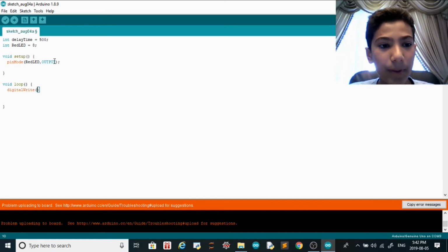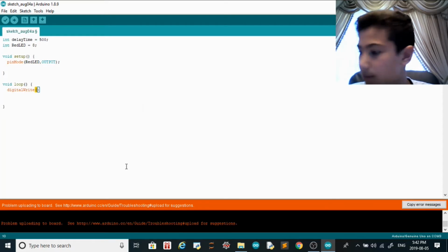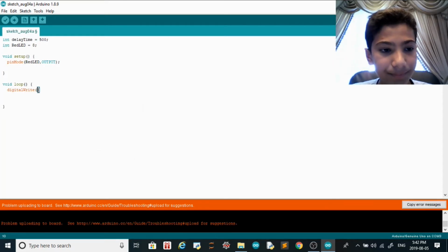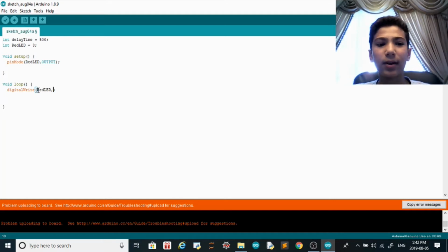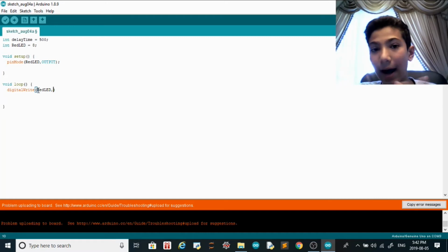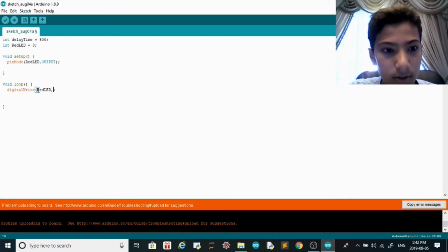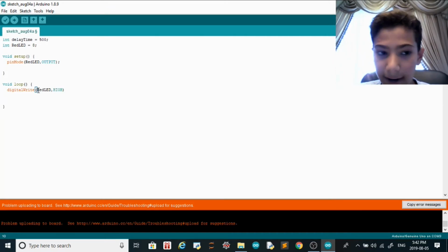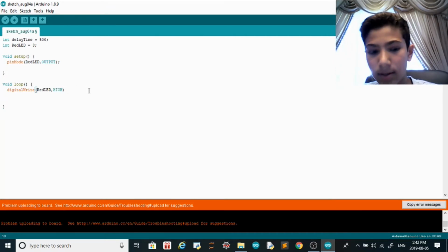So pinMode also takes 2 arguments, and digitalWrite also takes 2 arguments. So let's put red LED, right? And on the second argument, you can put HIGH or LOW. Okay, so HIGH is on, LOW is off. So I'll put it HIGH, right? Because we want to start high.